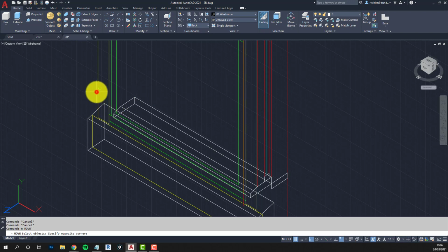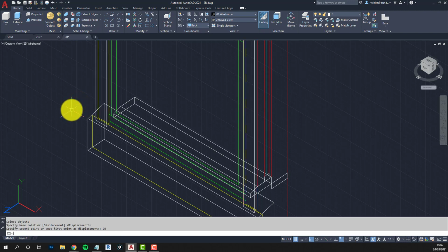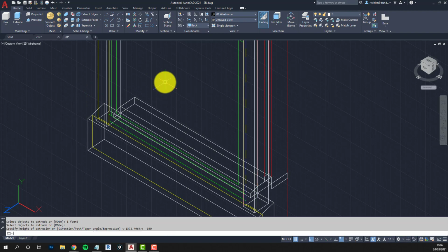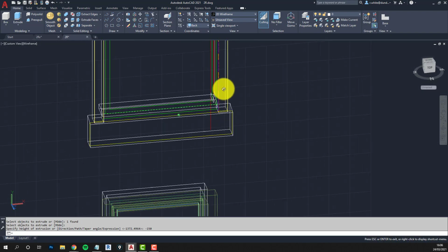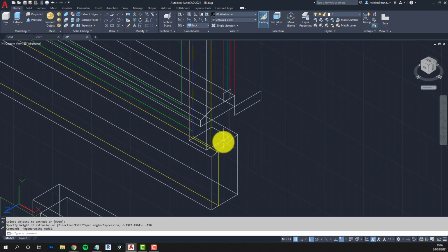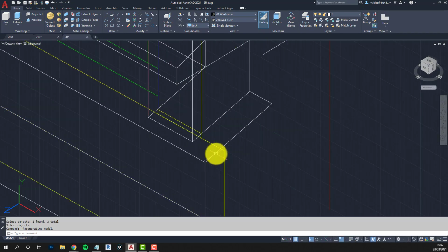So if I move this initially by 25, but then extrude it back the other way by 150. So it's minus 150. Okay, so we've got a bit of a merge going on in this corner. So let's see what these two shapes look like when they're joined together if we union them. Okay, so it looks quite good, looks quite stony like that.